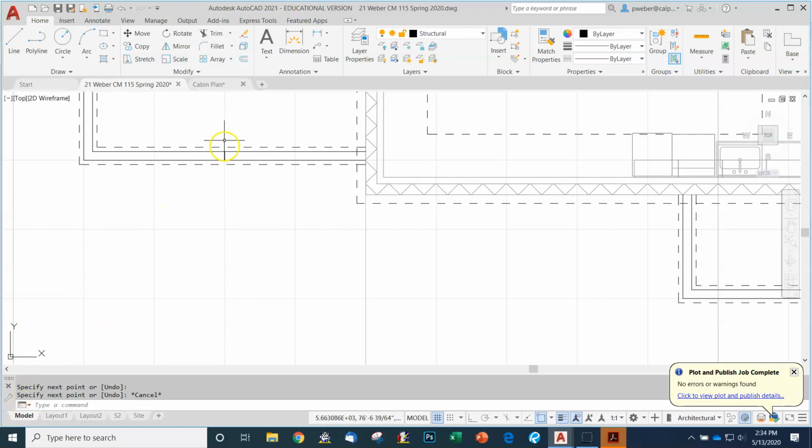So half of that, if we have a 9'4" opening, half of 9 foot is 4.5 foot, which is 46, another 6 is 52, about 54 inches. I believe if I offset this line 54 inches on both sides, let's give it a shot. I'll offset. Type in 54, click on this line, throw it out to the side, click on this line, throw it out to the side. Good, and click. Press escape.